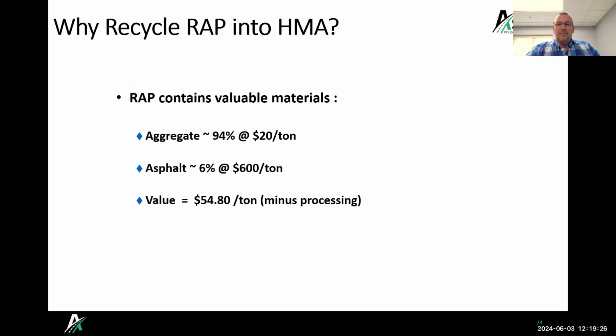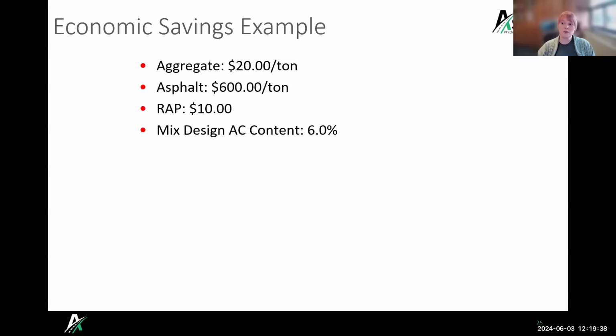I like to tell a lot of people that's probably more than we spent to place that asphalt that we're milling up and reusing into our new mixes. So it's really a great return on investment. You had a RAP question, Ingrid? Yeah, can RAP be used in the top course? Yes, RAP can be used in any course, and I'm going to talk about the best practices on how to use RAP here in a minute.